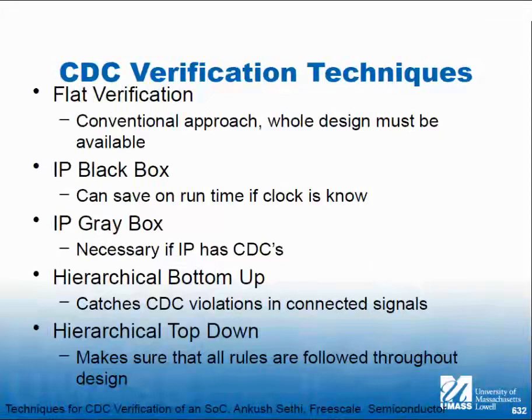And we talked a long time ago that there are ways of modulating the edges on clocks. So you might have a 100 megahertz clock and a 100.001 megahertz clock. Be careful when you say 100.001 megahertz, because simulators are time-based, not frequency-based. So when you say 100.001 megahertz, take the reciprocal of it, and that'll tell you how many picoseconds that is.